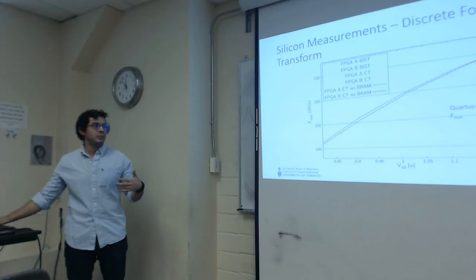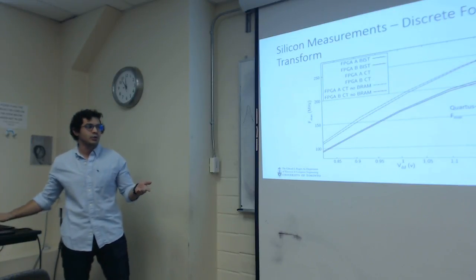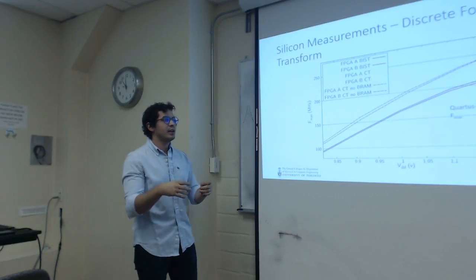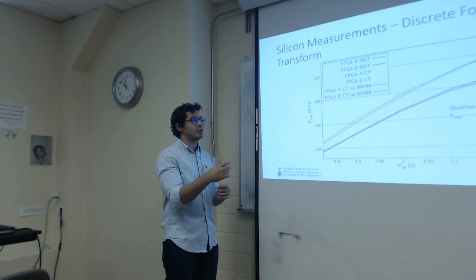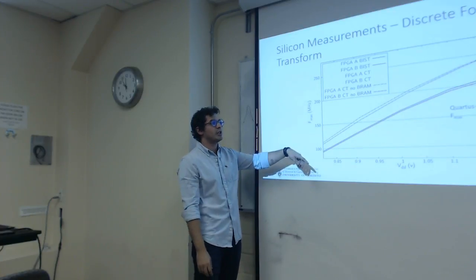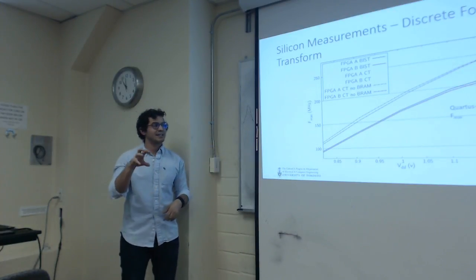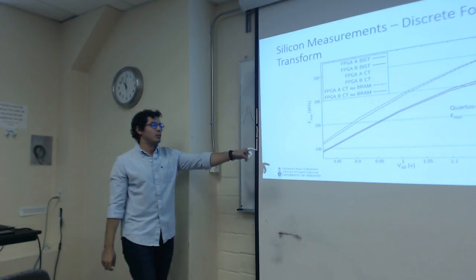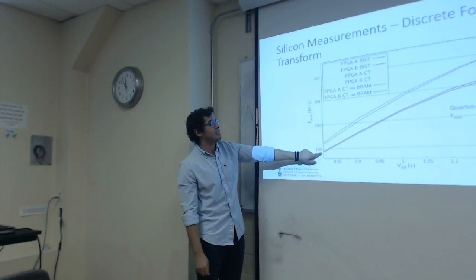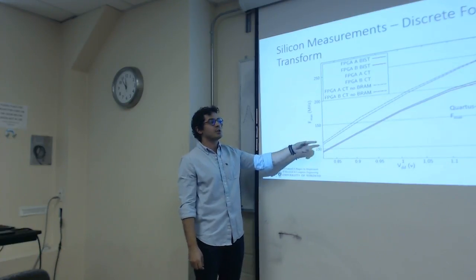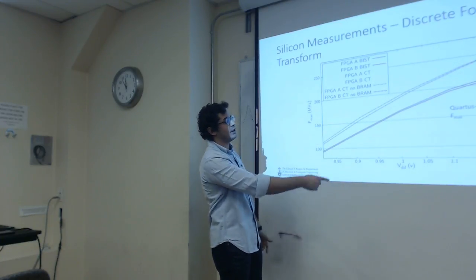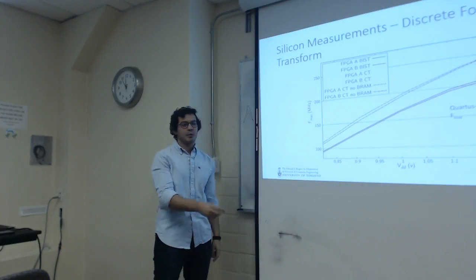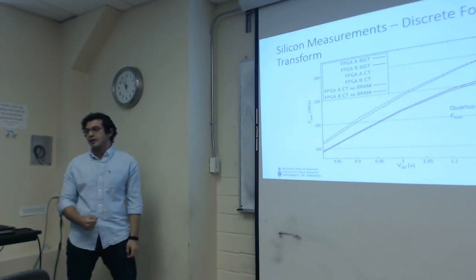So it looks great, but is it safe? To answer this question, we tested the benchmark itself to see if it fails or not, and we got these two solid curves. These two solid curves came from testing the benchmark itself on silicon. And what these two curves say is that the calibration table that we got is actually unsafe. It overestimates Fmax significantly, right? It tells us that at 1.2, we can run all the way up to 250 megahertz, but the application would actually be failing timing at that point.